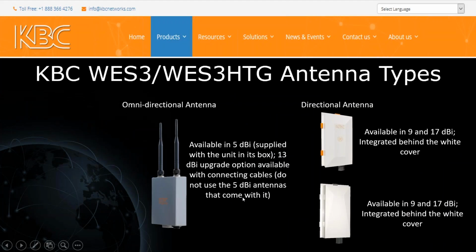Okay, the different types that we have, as I mentioned a moment ago: we do have the omnidirectional antennas. We use them for when both sides are in movement. So for example, maybe a crane application, or maybe our mobile surveillance units would have one of these on there. Something where it needs to be deployed for a certain amount of time in one place and then moved somewhere else, an omnidirectional antenna would make sense. An omnidirectional antenna would also make sense if you have one receive location and multiple transmit locations around it in a 180 or greater type angle.